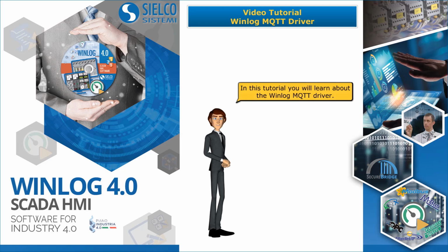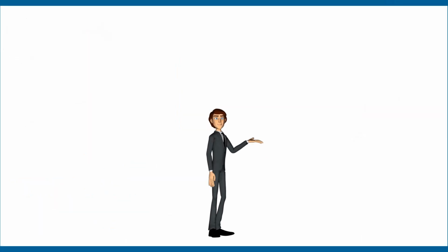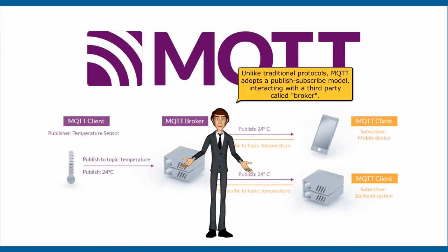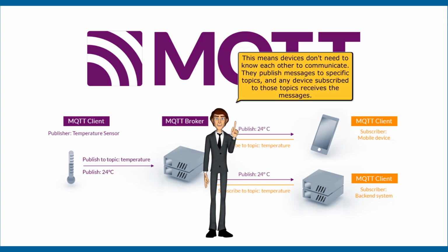In this tutorial, you will learn about the Winlog MQTT driver. MQTT is one of the communication protocols of Industry 4.0. Unlike traditional protocols, MQTT adopts a publish-subscribe model, interacting with a third party called broker. This means devices don't need to know each other to communicate. They publish messages to specific topics, and any device subscribed to those topics receives the messages.